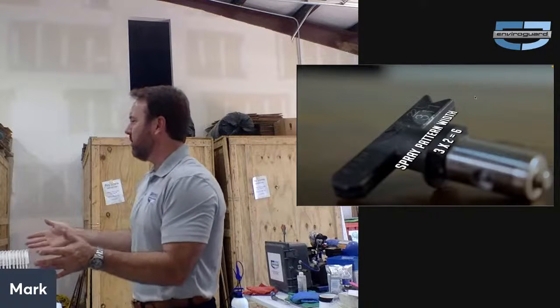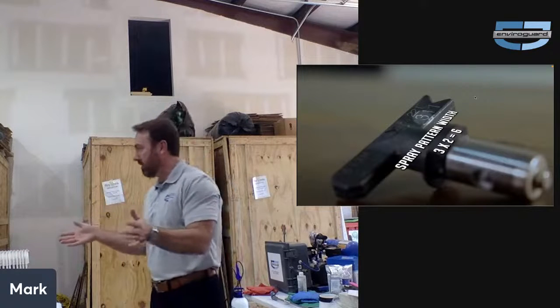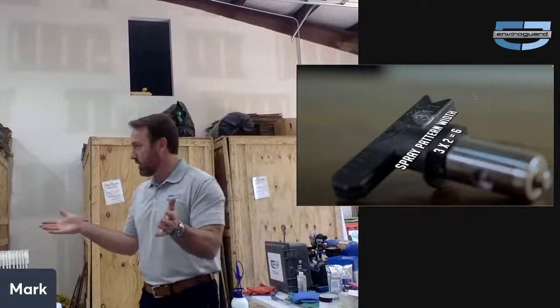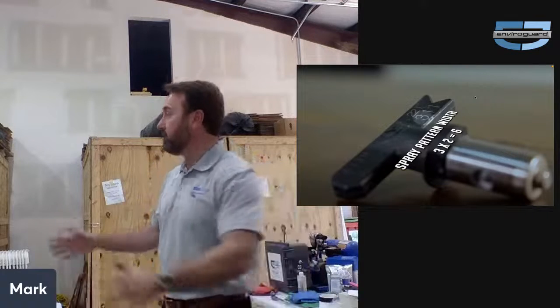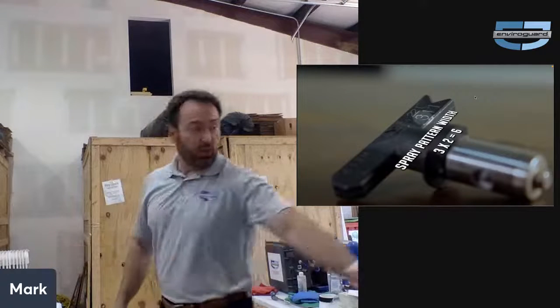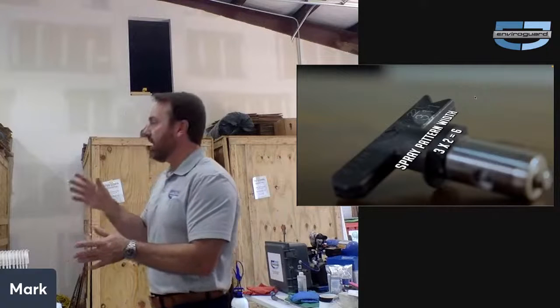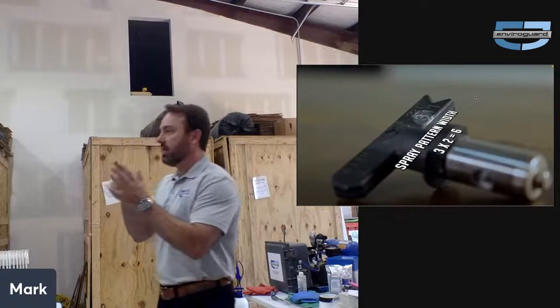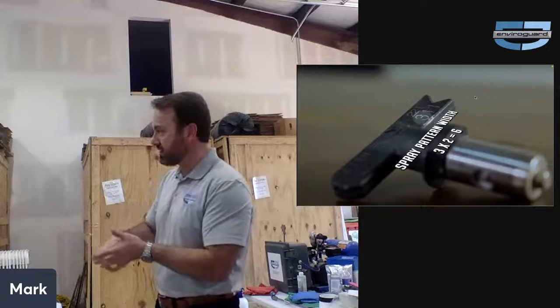You would think that they wouldn't care about the multiplication. They would just name it a 6 to begin with, so you didn't have to think about it. But this is the system that we're stuck with. So whatever the first number is here, multiply it by 2, and 12 inches from the surface, that's your spray pattern. Your 11 is 11 hundredths of an inch, and it always goes in odd numbers. 9 hundredths of an inch, 11 hundredths, 13 hundredths, 15 hundredths.